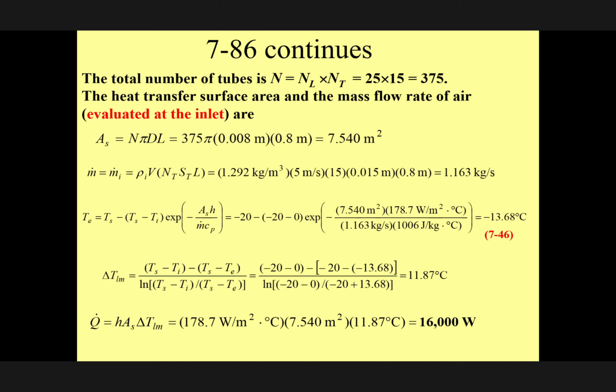It was concerning the question from chapter 6 about the steel plate going into a furnace. You mentioned that we used the conductivity K of the steel to find the temperature gradient within the steel. But didn't we just say that it was a lumped system, so all the temperature within the steel is the same?